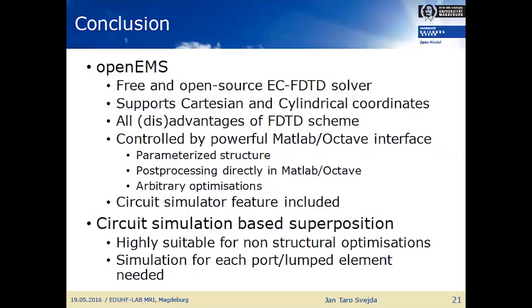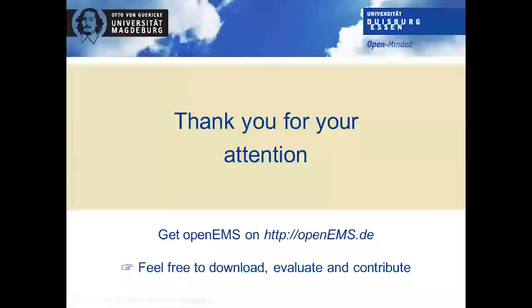So the problem is if you make any change of your structure, of course, it's not a change of your lumped elements, and then you have to do the whole simulations again. So if you have different phantoms or whatever, you have to do every time new full wave simulations. But if you only change lumped elements, you can do it in this way very quickly to tune these lumped elements. That's it.